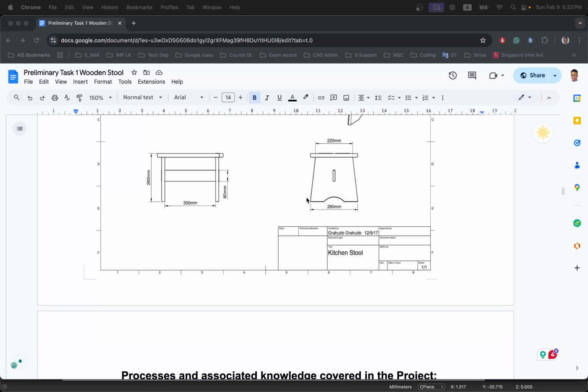I'm going to click on the top, where I usually click on the 0 point here, and I will type in the number 360. You can take a look at the top left corner here. You can just click the function and then enter the dimension. I'll use 360, press space bar, type in 280, press space bar.